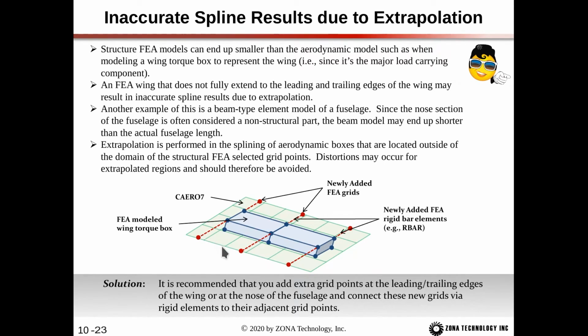Now when we add these grid points and the R bars, of course that's not going to affect your natural, your generalized frequency. It won't affect your mode shapes. However, we're just adding these points to make available to us for the spline.